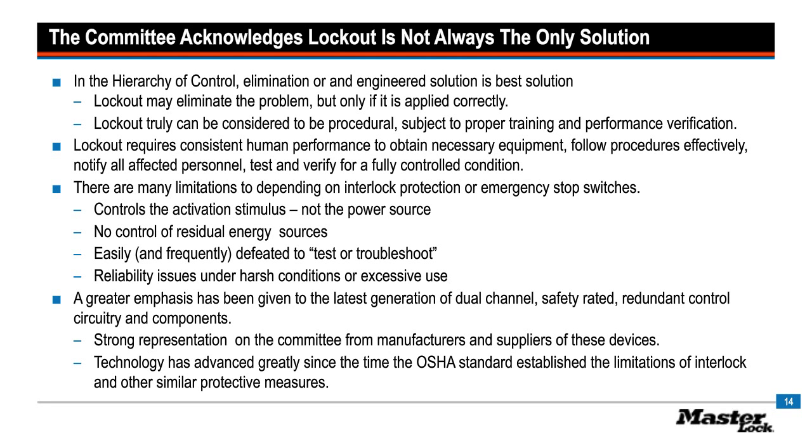And so we find that when a risk assessment fully considers the capability of protective systems alternative to lockout, a good decision can be made whether or not you want to consider that in lieu of lockout when your practicability statement has said we must have power for this task.